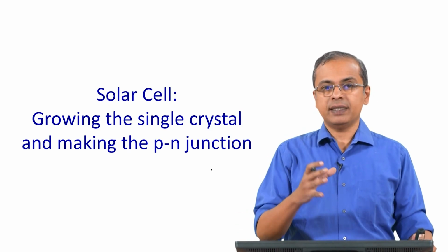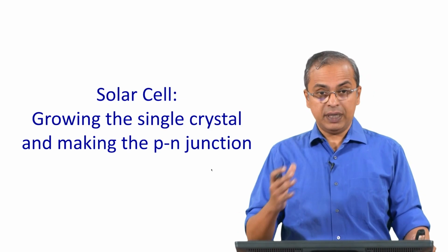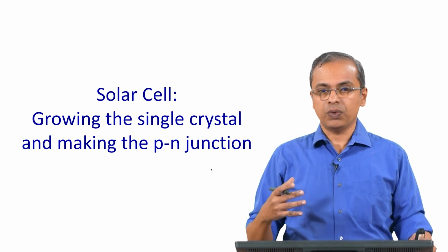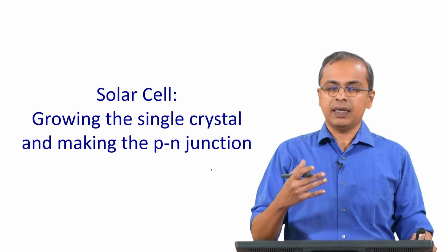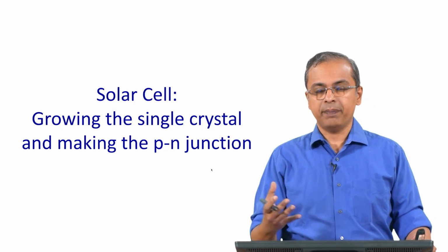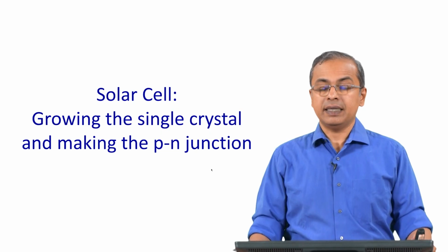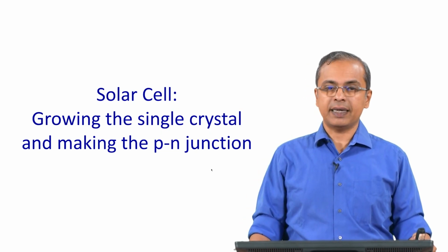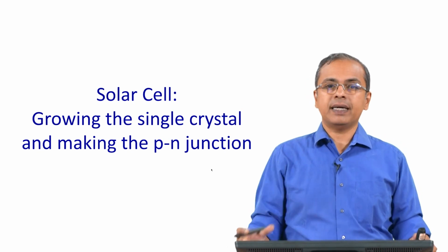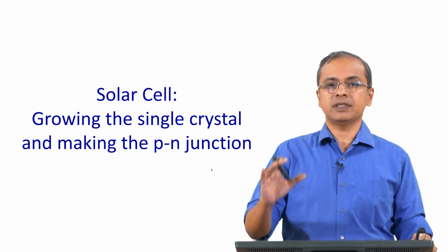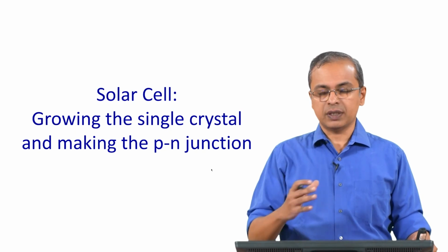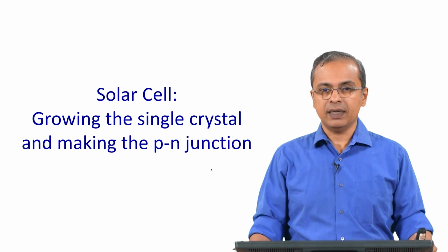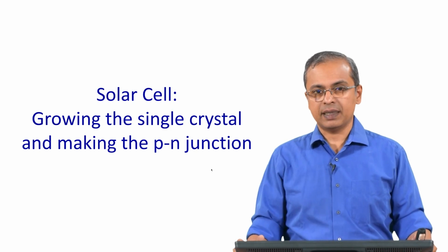When we looked at the semiconductor as an independent entity, we looked at its band diagrams and the origin of those band diagrams. We tried to at least briefly look at how the internal structure of the material impacts the band diagram, and how the behavior of the electron with respect to that internal structure creates that band diagram. We also looked at those flat band diagrams, and the E versus K curve and how the interactions between the E versus K curve and the periodic structure of the element creates the band diagram for you.